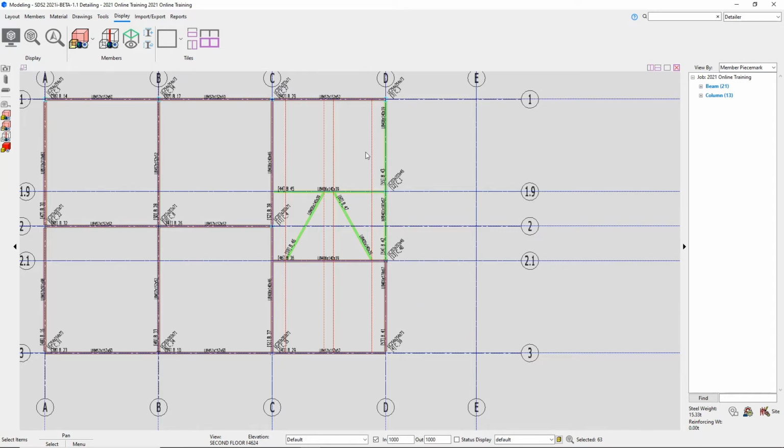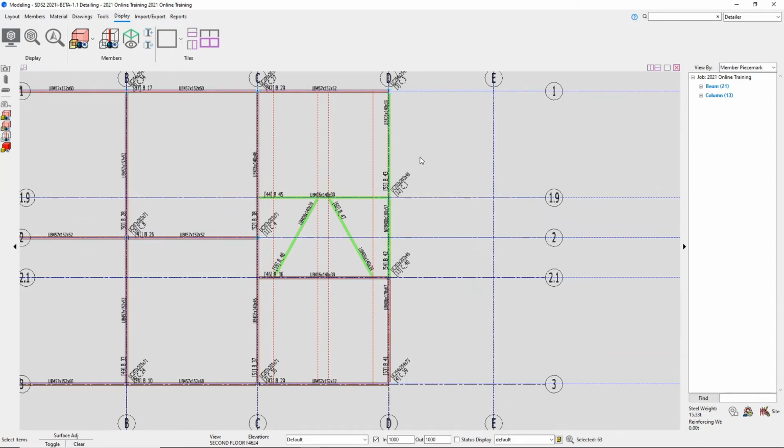Another thing that we can do here is if we hold Shift and Control, we can see that the left click is now toggle. So if I highlight over, say, this portion right here, we can see that those are all deselected. If I would highlight over that again, it would be selecting again. So it kind of works in that manner where it would both be selecting and deselecting things.